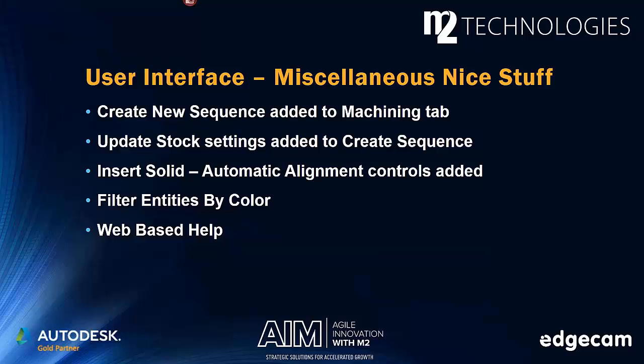That's still the way we should use the software. However, there have been cases, I've done it myself, where you get started, you go over to the machining tab, and you see the note that you have to make a sequence first. And oh, shoot, I forgot to do that, and head back to setup. You don't have to do that anymore. You can do that right from the machining tab.